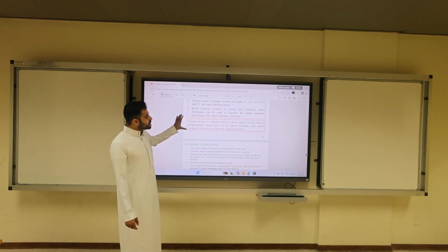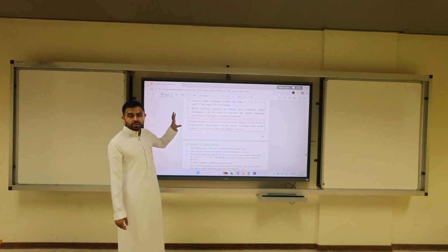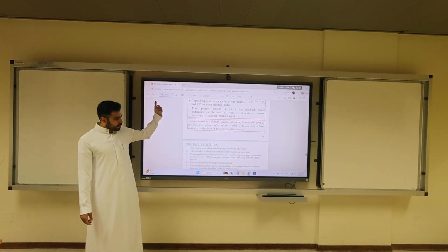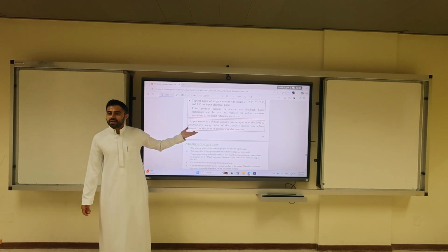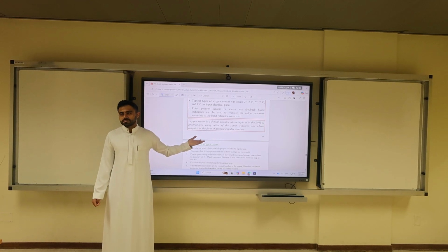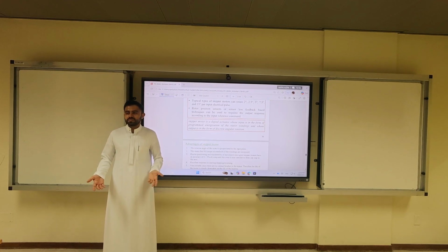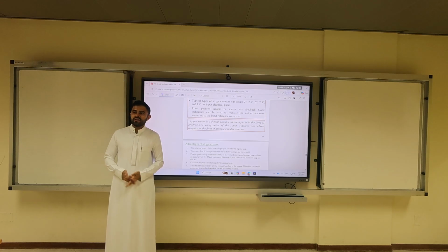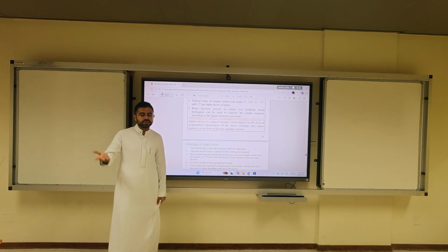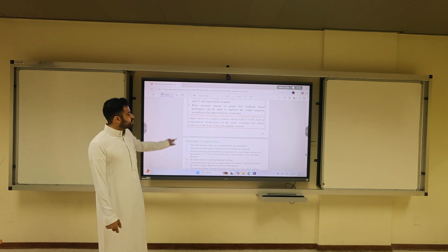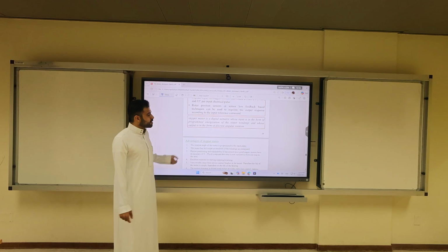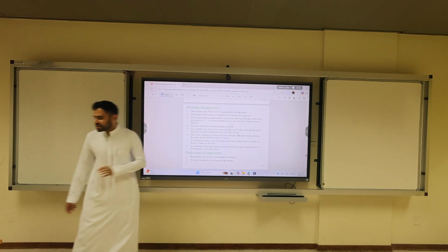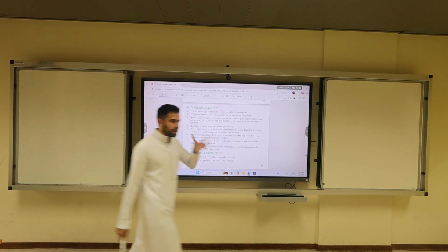So the stepper motor is a digital actuator. It's a corresponding digital motor, machine. Should we have a stepper generator? No. There are things that don't make sense. A stepper generator should not exist, because having a mechanical precise movement is not realistic. It's in the form of programmed energization of the stator winding, and whose output is in the form of discrete angular position. Let me explain to you just how it works.